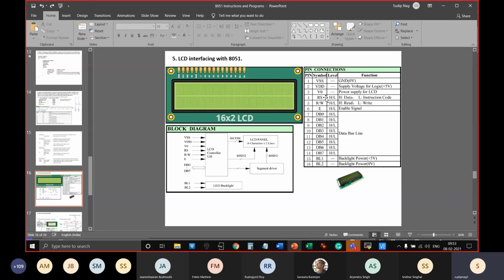Then there is the register select. This bit is there to select different registers. In this traditional LCD, there are only two registers, the display and command registers. So this is just a 1-bit operation. In modern LCDs, there is no such pin. Instead, there is a softer way where 16-bit or 32-bit registers are there inside, through which you select different registers. In this old LCD, there are only two registers, so a 1-bit high or low combination.